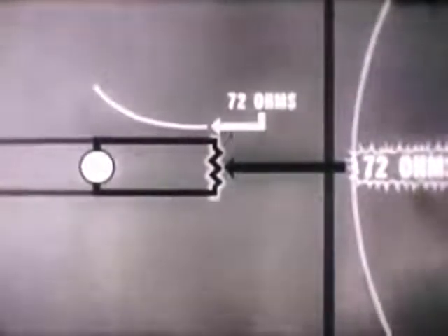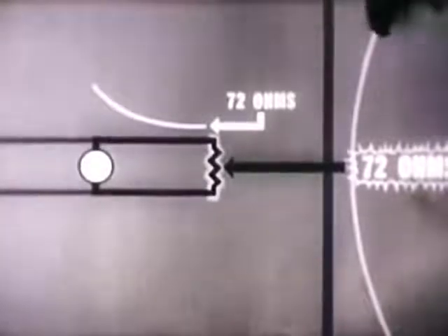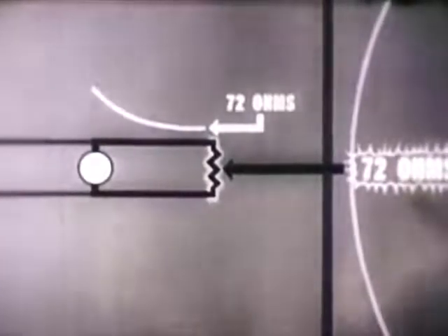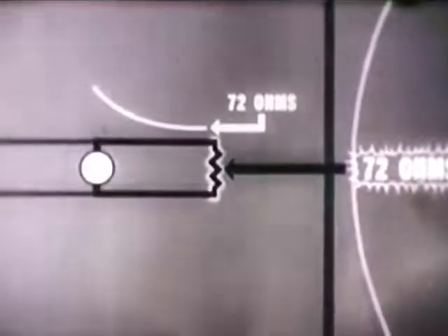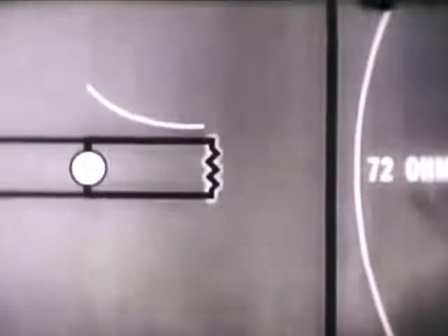This changes our curve a bit, decreasing the impedance value at the generator end of the line because the standing wave is no longer at maximum amplitude. Now let's bring our antenna into the picture again, connecting it to the closed end of the line and removing the resistor. As the characteristic impedance of the transmission line is 600 ohms, it remains for us to match this value at the junction with the quarter wavelength line.